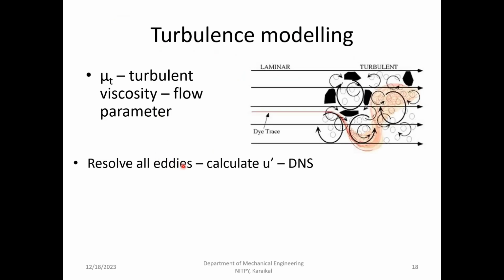So now, okay, if we don't want to model this, I'm saying that I can go with very small measures and very small time step size, then I'll be calling it as a direct numerical simulation. You will be requiring around 1 million cells in a size of around 1 inch cross 1 inch cross 1 inch to look at how the flow is developing. So that is a general kind of numbers they are looking at.